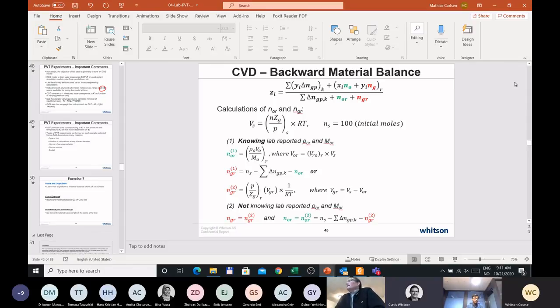I think at the top of the list would be oil relative volumes, meaning that you measure both gas and oil volumes in every CCE test conducted, even for lower GOR oils.